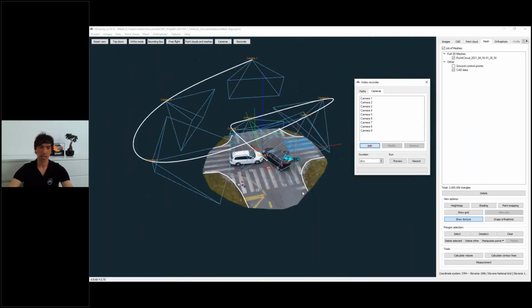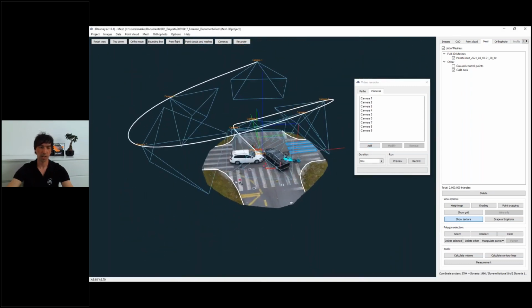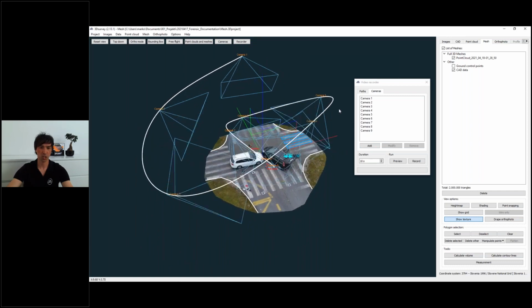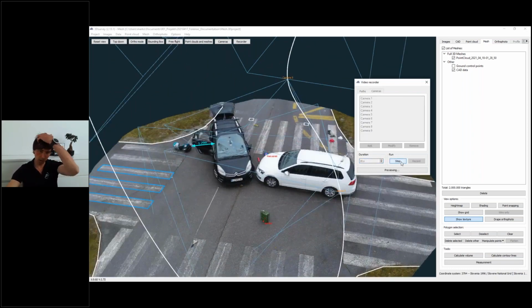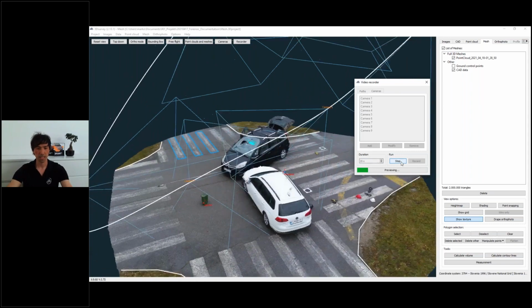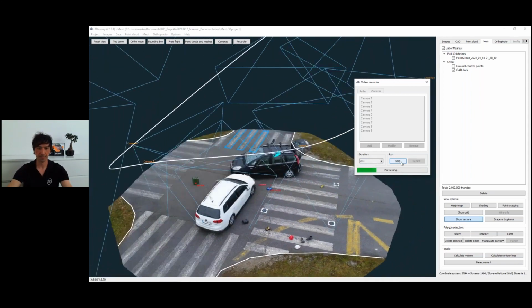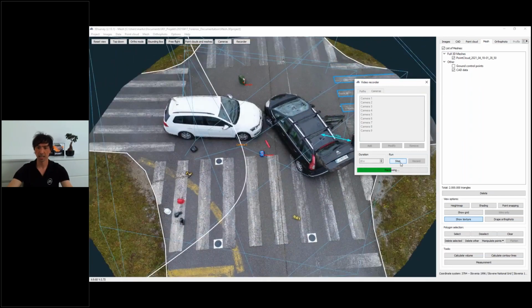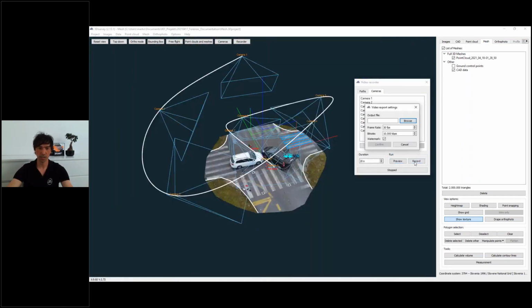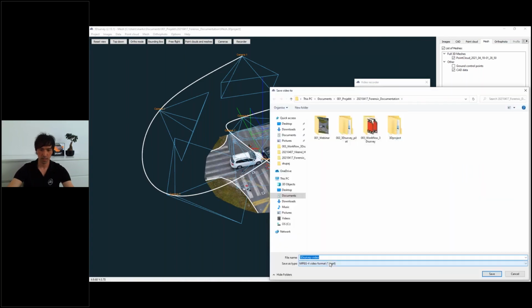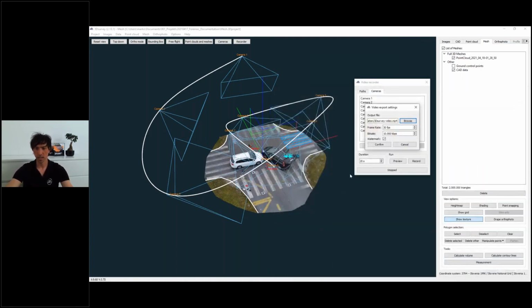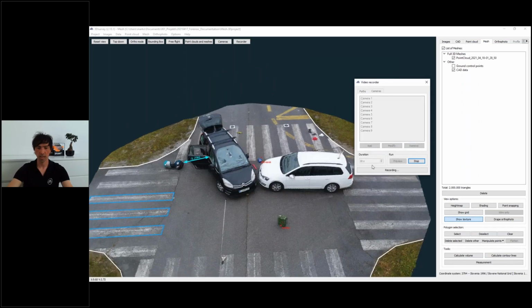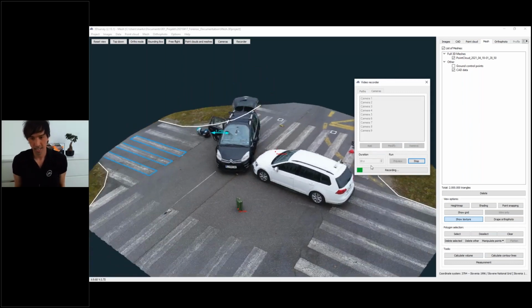and out. And you can see here my camera positions, the white line is showing how the camera will fly. The total duration should be, let's say, 20 seconds. And I can go in a preview mode and immediately see how fast it is. I see the speed is okay, the perspective is fine. Let's stop the preview and start recording mode. So yes, this is okay. Confirm, and right now we are recording this.